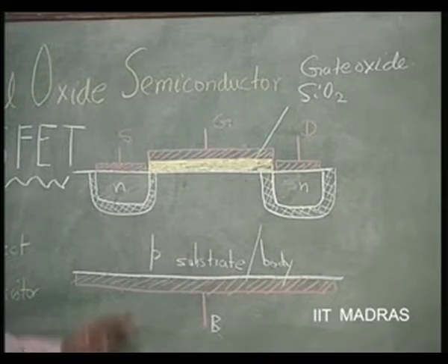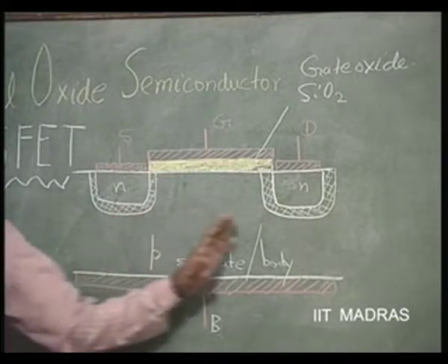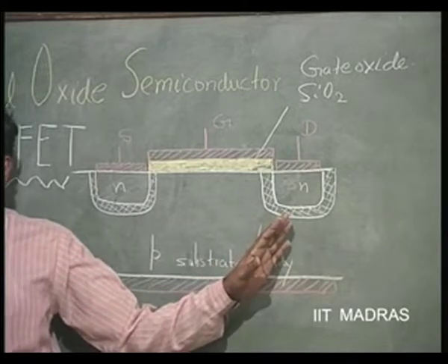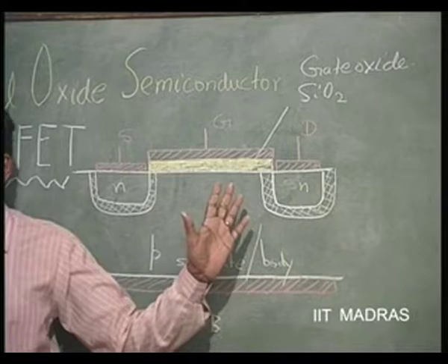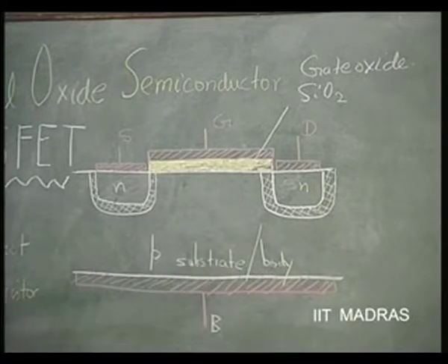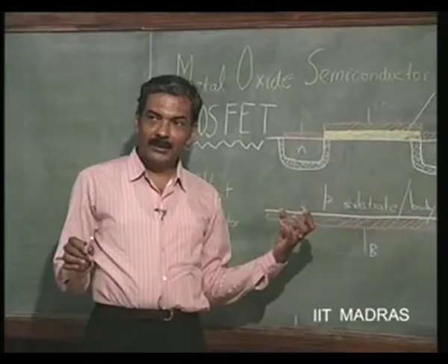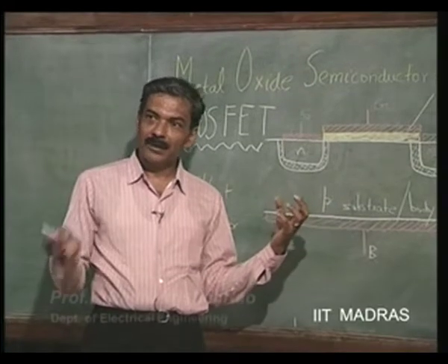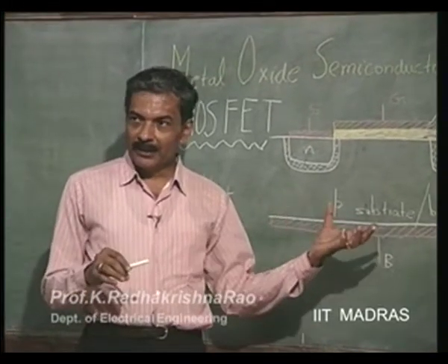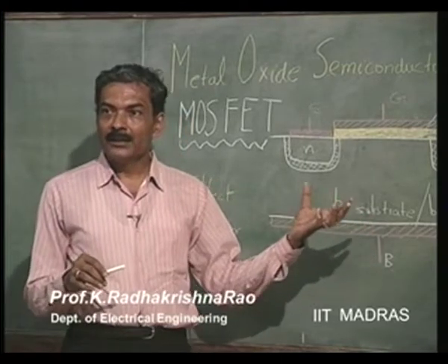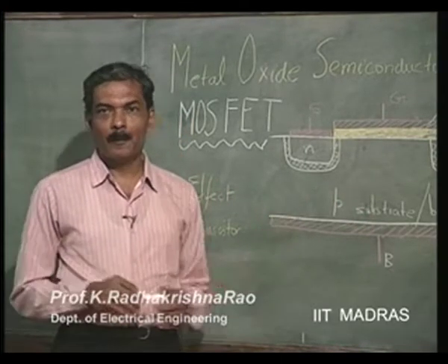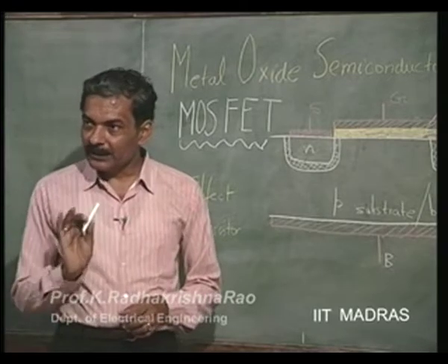Under this situation, let us understand what happens. We all know that the p type material has majority carriers as holes and minority carriers as electrons. The overall charge of the whole thing is space charge neutrality, right. For every mobile carrier, there is an immobile atom left there which is charged in the opposite way. In this case, for every hole there is a negative charge which is immobile. Overall space charge neutrality is still there in the whole thing.